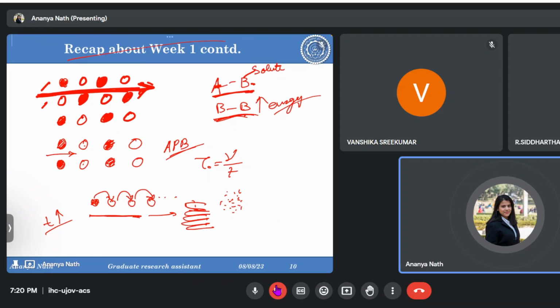So as the dislocation further tries to break the barrier of the atmosphere and tries to move further away from the atmosphere, there will be another stress acting on the solute. Solute will again try to catch up with the dislocation or will try to restrict the movement of the dislocation. So it is a thermally activated process.